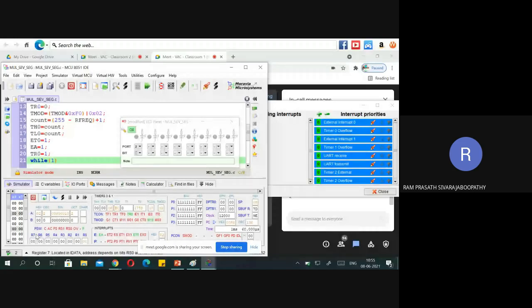You can see the count value also. One time interrupt occurred, correct? One time the interrupt has occurred. Now also the LED is in off condition only. So what we are doing: if it is less than 2, what we have to do? T plus 1. After doing T plus 1, we are going again. So again it keeps on waiting. First 250 microsecond timing is over. Now the next 250 microsecond timing is getting generated.